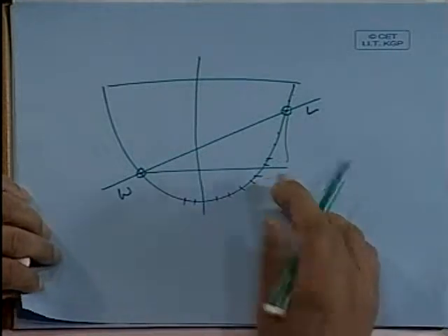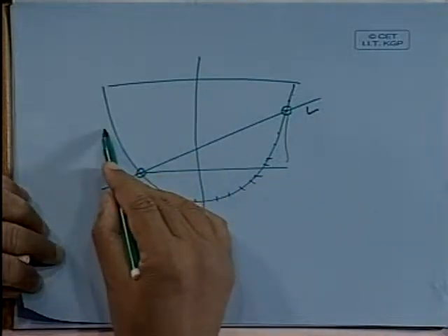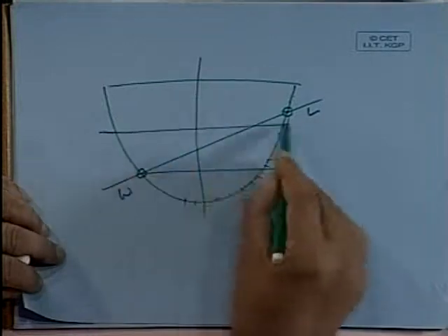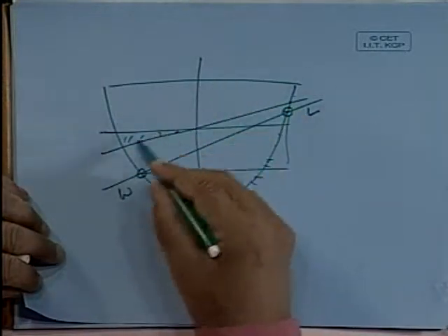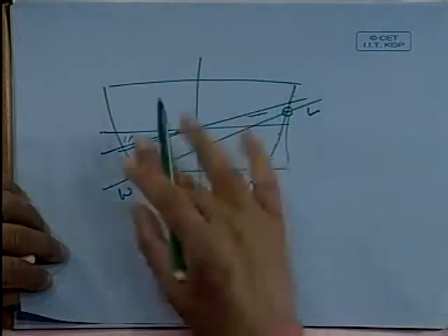Some of the earlier books used to have the wedge method, where you try to find this area, the difference between the two, and then shift it slightly, etc. There were a number of methods there, but for a course, it is not important for us to know all the methods, as long as we know what is to be calculated. As I said, what we need to calculate is the area under that and the two moments, and add them up.